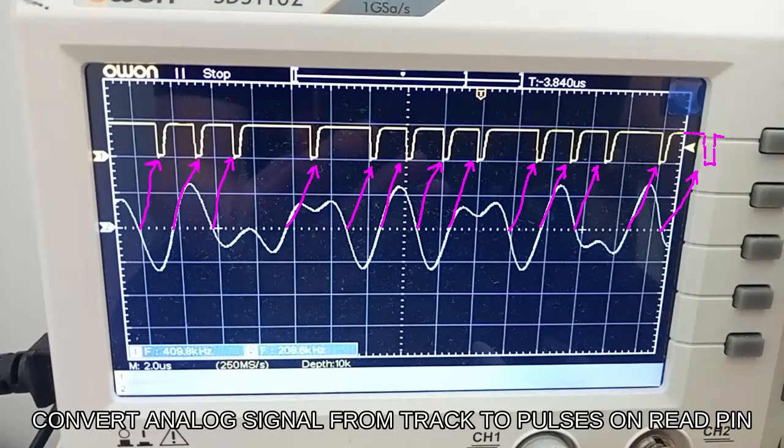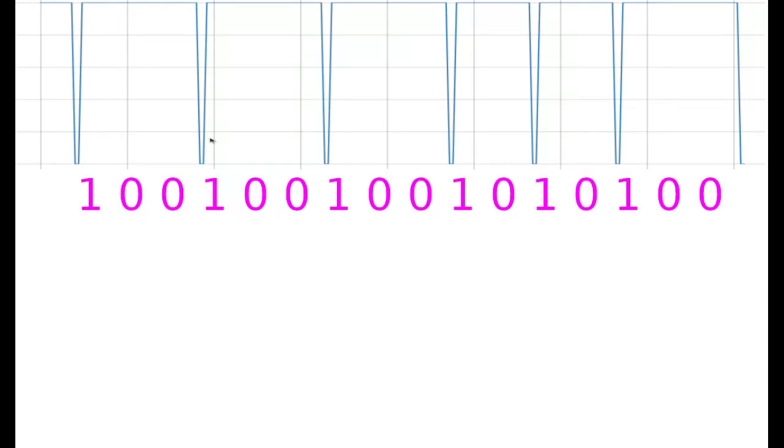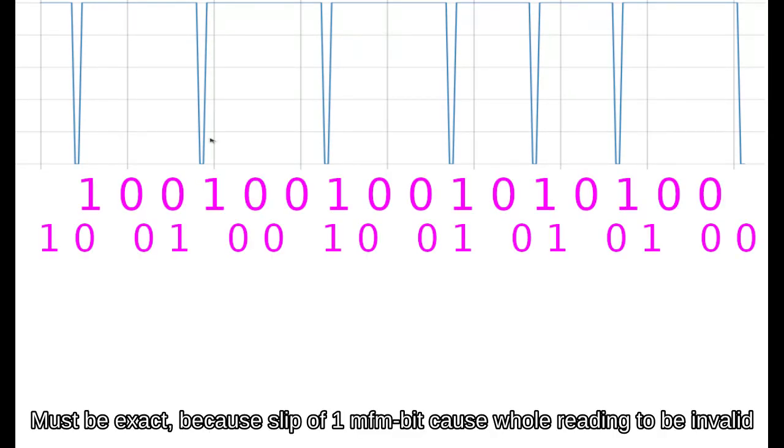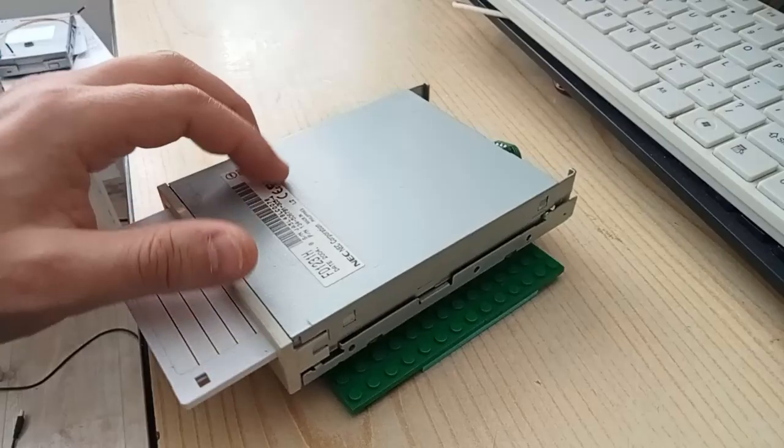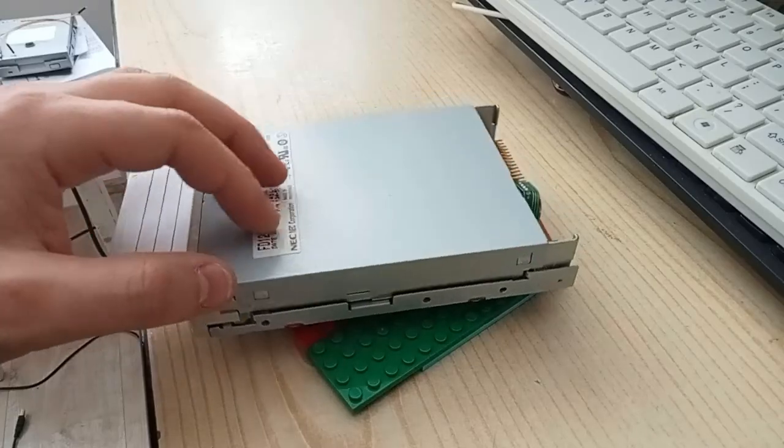Here is an example of MFM decoding. Start from measuring pulse lengths. Then translate them to MFM bits, then divide MFM bits into pairs, then decode pairs to byte bits, and form a byte from bits. Each track begins with a track start header.